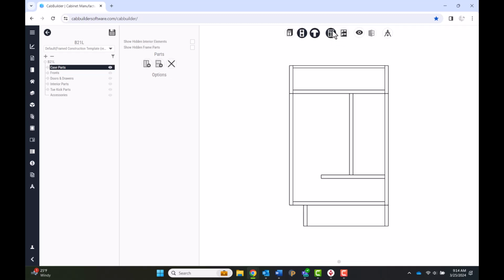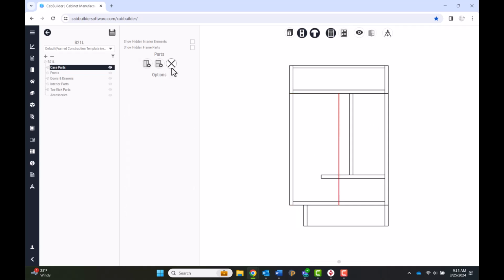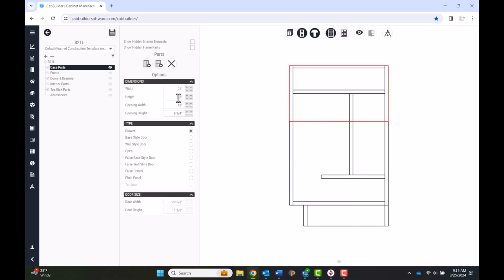Front Sections works in much the same way as Inside Sections, but the elements are defined by the openings between the splits rather than as the divisions themselves. Select an opening to see the element and its attributes in the middle column. To add an element, split an existing one with either a vertical or horizontal division. This will automatically add a mid-style or mid-rail in that position when working with framed cabinets. To delete elements, select Splits and click Remove.